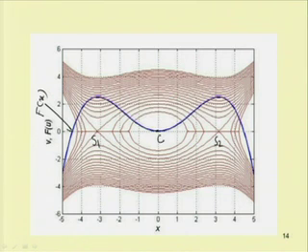So, between these two saddle points we have a periodic response. You can observe that the response is periodic here because it repeats. Similarly, here the response is periodic, and here the response is periodic, and these separatrices, which connect S 1 and S 2, separate this periodic response from other types of response. So, these 2 points S 1 and S 2 are unstable points and C is a stable point. So, for example, if you take a particular value of h here, when h equals the same, we can have this 0 velocity, and before and after this point.